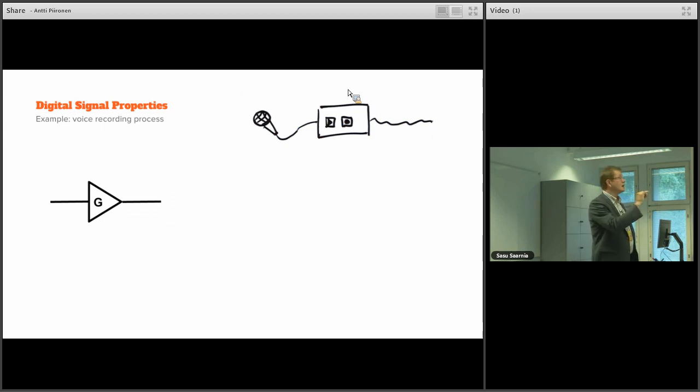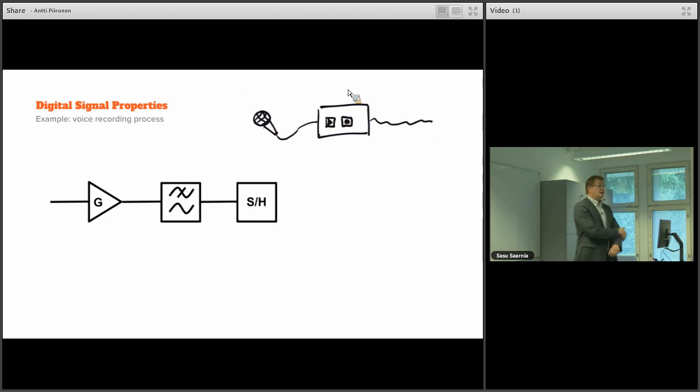Are there electronics students here from the degree program of electronics? No? I was expecting, but okay. But anyways, you know what that actually means. So when we have a sensor like a microphone, it gives a very small signal. It's just a few millivolts peak to peak. You need an amplifier. And then the next step is that funny box in the middle, which is a low-pass filter.